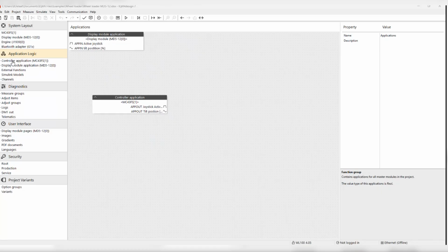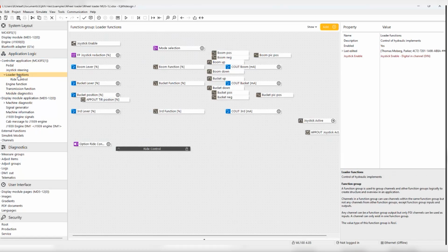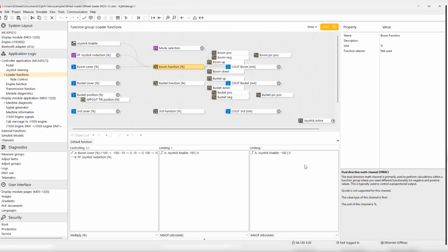This is the application page where the machine programming resides. This page contains a range of function blocks that actually define the program. The typical layout would be inputs and function parameters to the left, outputs to the right of the panel, and all of the math and instructions to run the program in the middle. Every function block has a specific control purpose with its own set of rules and parameters. This is where you can create the instructions, rules, and limits for that block.